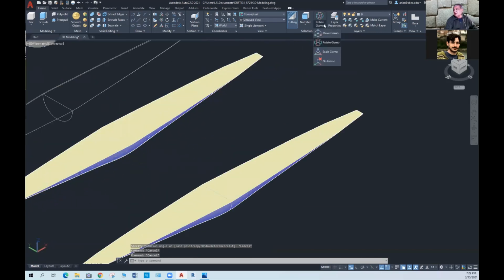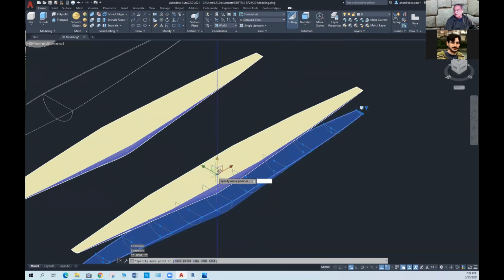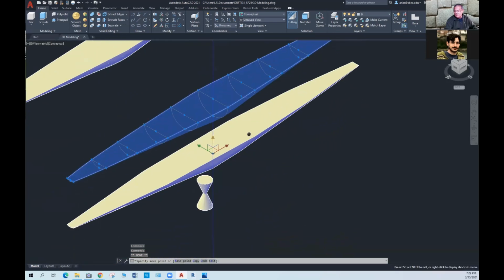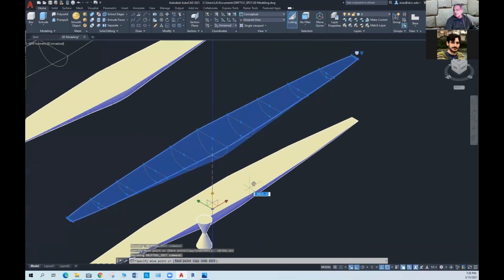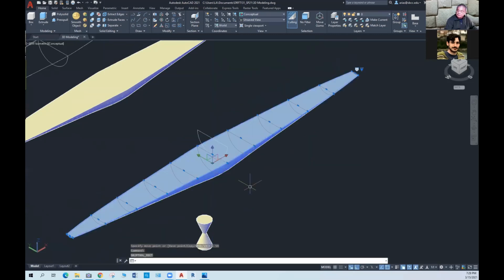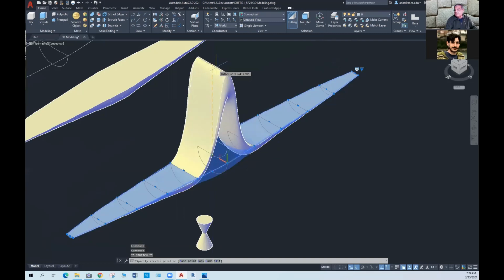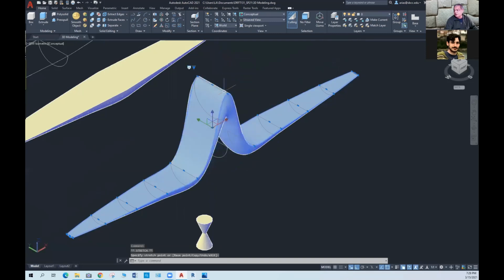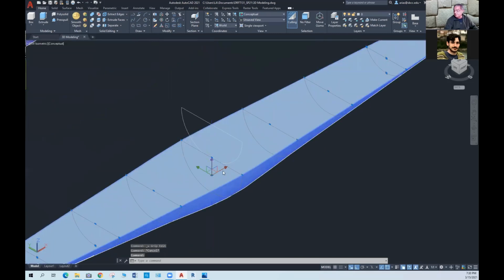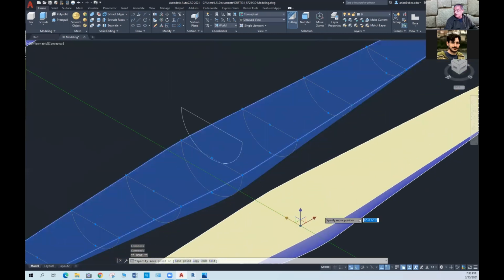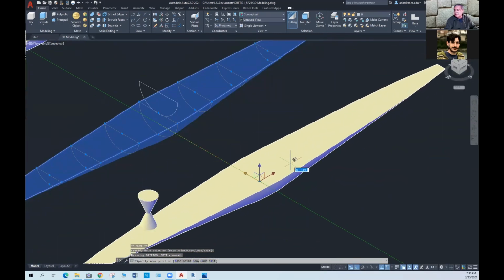The same with the other gizmo, the move gizmo, right? So I click on, and then I can move on that axis. It's always going to be on the particular axis that I selected. And now I can just enter the distance, right? I don't have to type move, and I don't have to type the direction, right? I just click on the axis and perform the function.